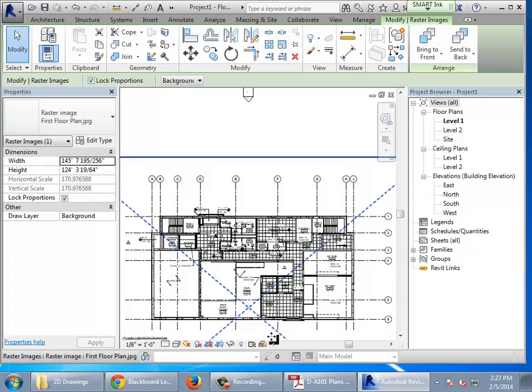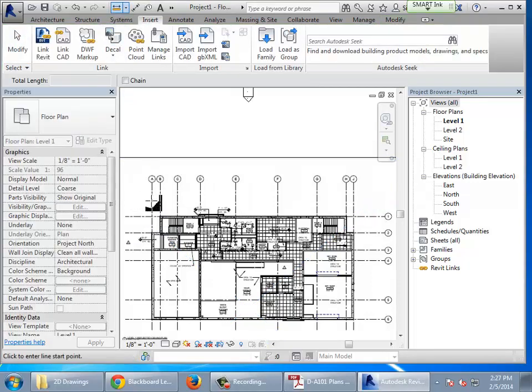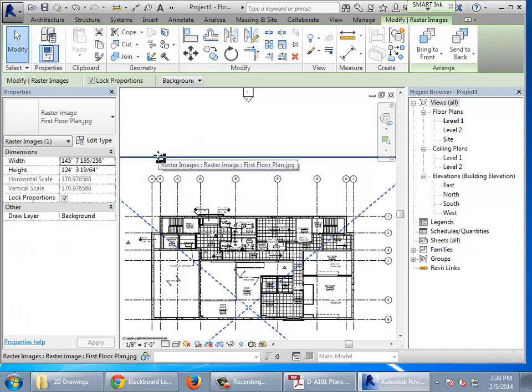Here's the deal. We'll come on over and do a little measuring. We can grab our little measuring stick, which is up there in the toolbar. And I can drag from this point all the way over to here. And you see it's currently 79, 81 feet, something like that. So not quite right in terms of what we have in mind. We need to make it bigger. You can go through and do the math. Given that ratio, I need to make it 150% the size, whatever it is, stuff like that. But I think we ought to be able to do this even graphically. So let me see if I can get that to work for you.